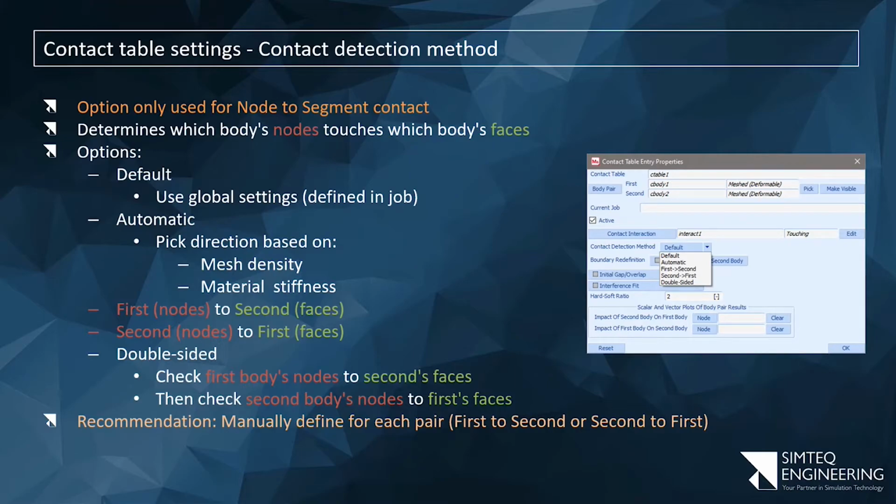But then what you typically find is there's some nodes that should have made contact, but due to circular dependencies in the equations and so on, it's not possible. So some nodes will be missed. Even worse, if I look at the contact status, instead of seeing on the one body this nice contact patch where it's touching, you will see it in some nodes on the one face and some on the other, and it's really difficult to figure out what the actual contact face is.